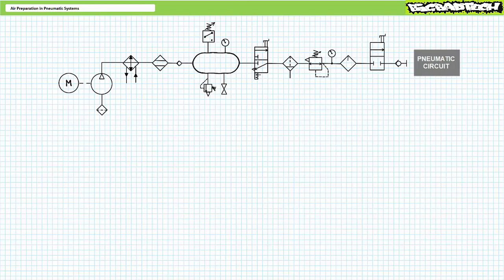Let's say a pneumatic circuit necessitates 100 psi at minimum to function properly, and a regulator is moved into a position that ordinarily allows 100 psi. However, unbeknownst to the day shift, the night shift operator in the midst of a goofball binge dropped the pressure switch's set point to half that at 50 psi, or worse yet, turned the motor-driven compressor off. What happens? I'll tell you what happens.